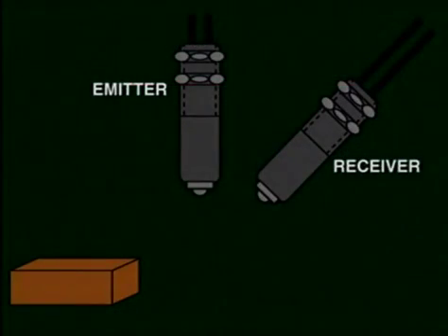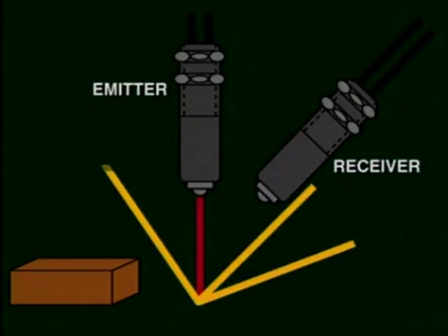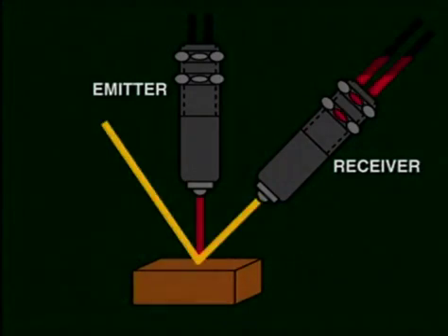The diffuse scan reflects a perpendicular beam of light in a diffuse manner off non-shiny or dull surfaces, and is reflected onto a receiver which is set at a predetermined angle, usually 45 degrees, to pick up any diffused reflections. The scanning distances of this type of device are generally limited to no more than 6 inches.